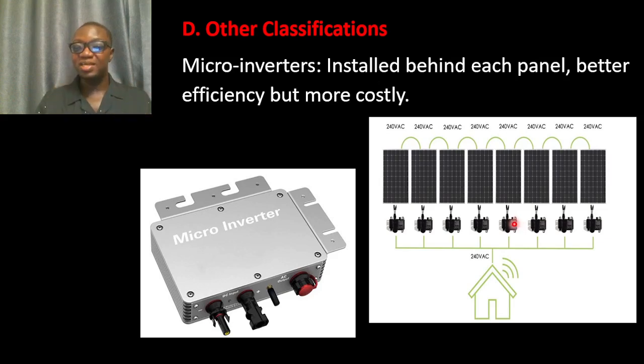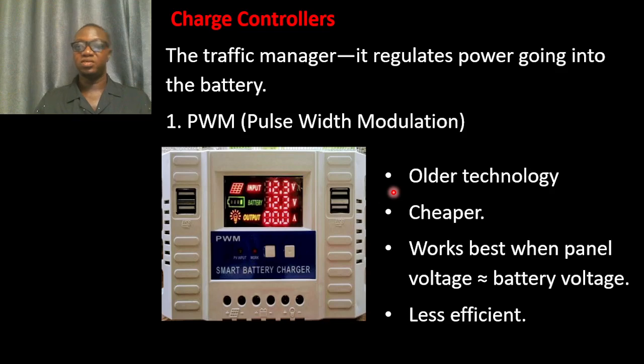And at the panel level, they generate AC current and supply directly to the house. So it is very, very easy to detect fault. When any panel is not producing well, you easily notice which panel is producing well, which panel is not producing well, which one shading is affecting, which one shading is not affecting. The energy management is very, very easy using this kind of inverter.